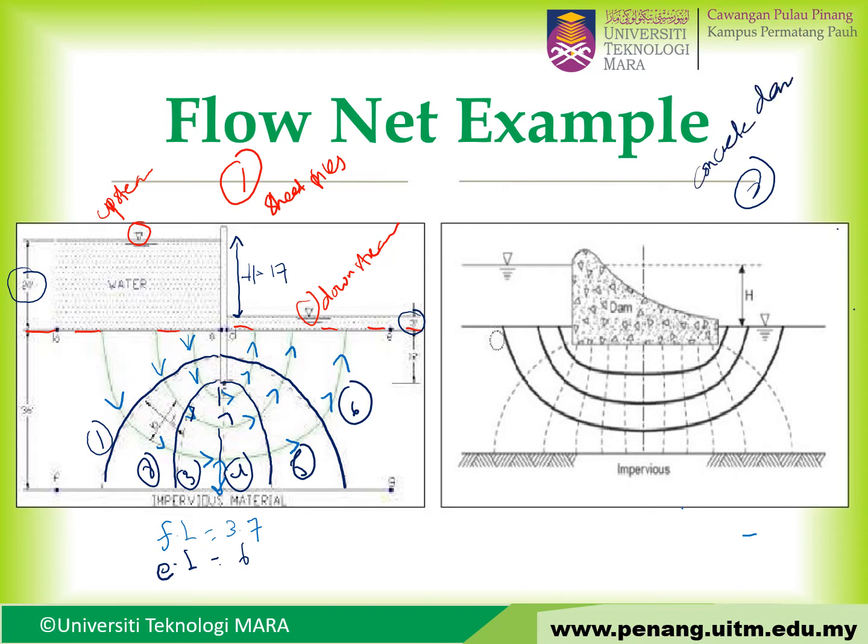Concrete dam. Alright, so as usual, you look at this. You have the upstream, you have the downstream, and this one is the ground surface. Water will flow from the upstream to the downstream. So you have to draw the flow line from the upstream to the downstream.